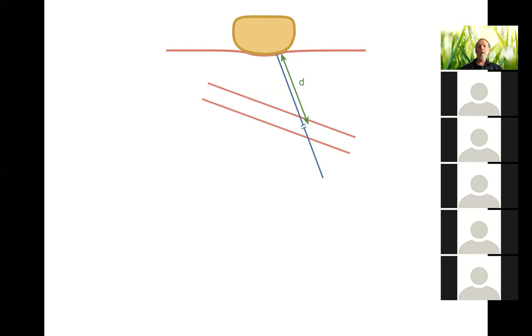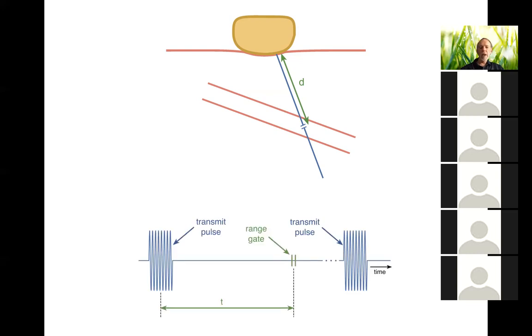As soon as you do that, the machine can calculate the depth, D, and so it knows the exact time the echoes will come back from that sample volume, and therefore exactly when to sample the echoes in order to detect the Doppler shift. And this is highly selective because the range gate, as I'm showing in the diagram below, is small. As I mentioned earlier, it may be a microsecond or less in size.